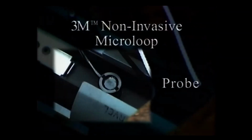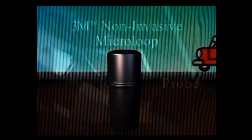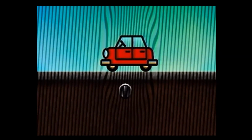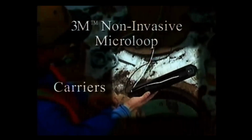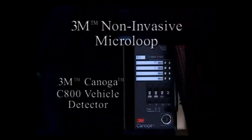The 3M non-invasive microloop system consists of a 1-inch diameter probe, which converts changes in the vertical component of the Earth's magnetic field to changes in inductance. So as vehicles pass, they increase the magnetic field at the sensor, allowing you to gather vital data. The system also includes carriers that hold the non-invasive microloop probes in a fixed vertical position, lead-in and home run cables which are used to connect to the vehicle detector, and the 3M Canoga C800 vehicle detector, which senses changes in inductance from the probe.